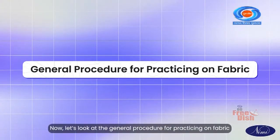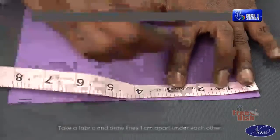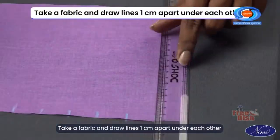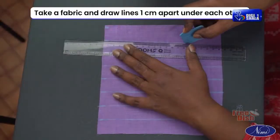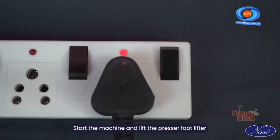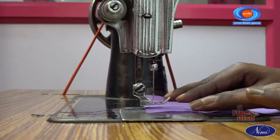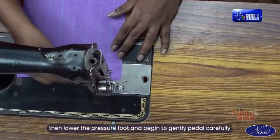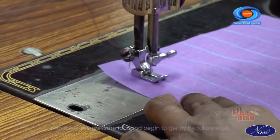Now, let's look at the general procedure for practicing on fabric. Take a fabric and draw lines 1 centimeter apart under each other. Start the machine, lift the presser foot lifter, and place the fabric under it. Place both hands on the fabric. Then lower the presser foot and begin to gently pedal carefully.